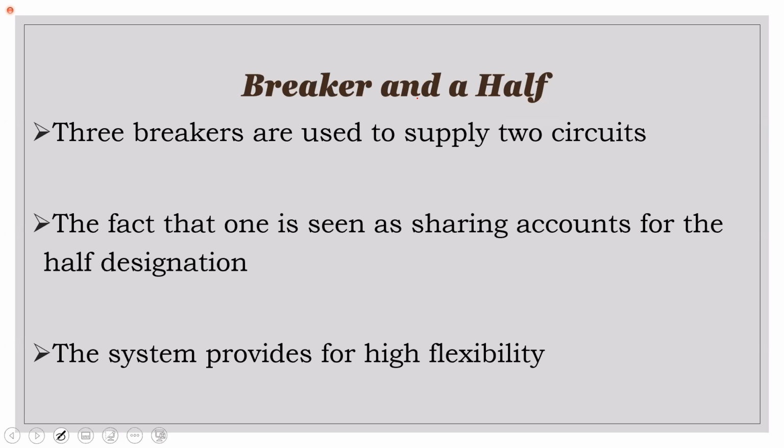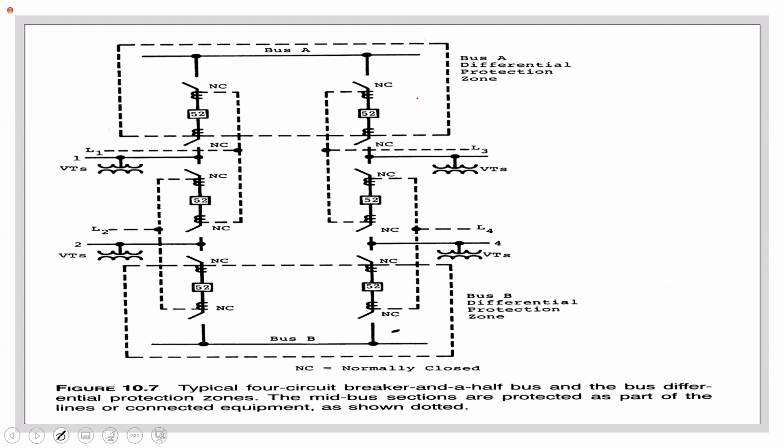And it is very flexible. Note that it is in the mid-range between double breaker, double bus, and single breaker, single bus. So it's in the middle there. In terms of your figure, this is what it looks like. That's your breaker and a half.